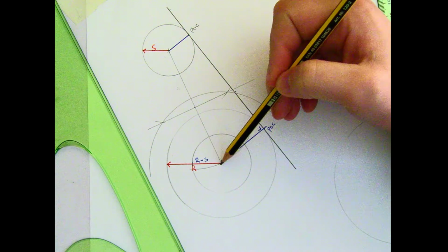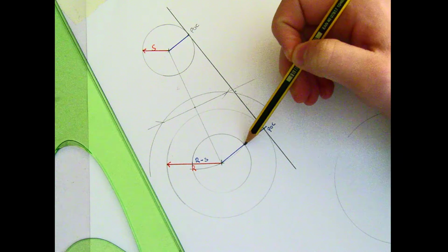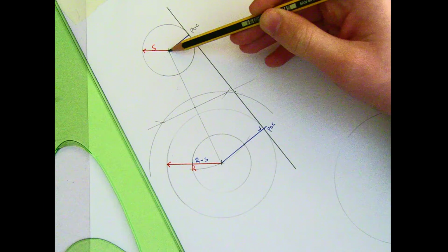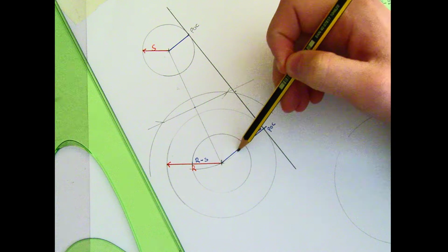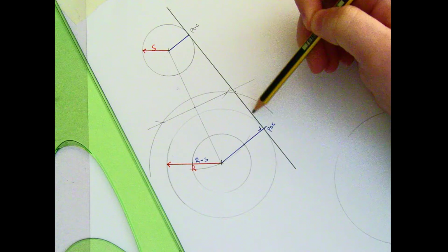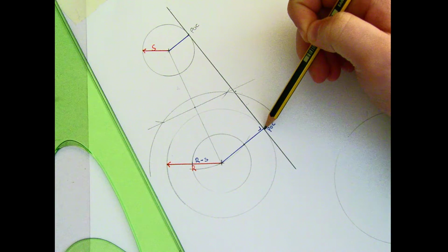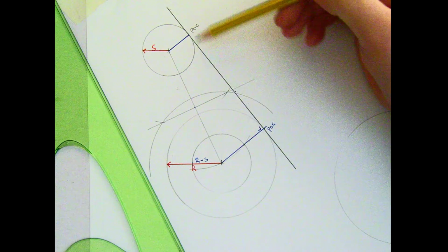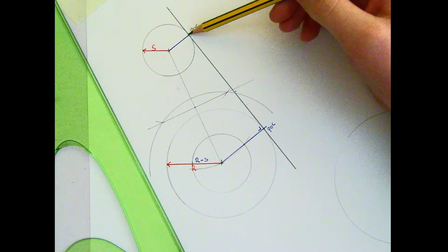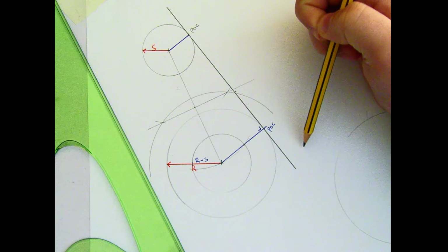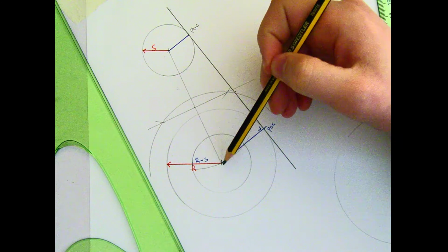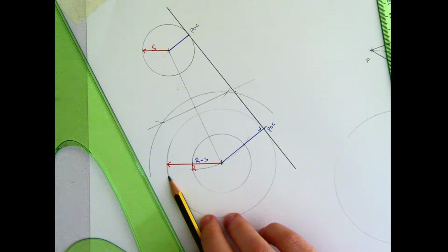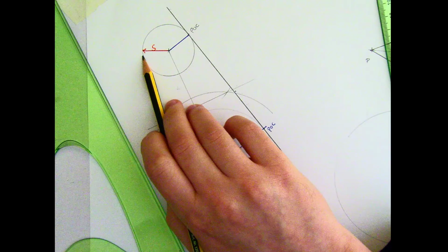join from the point to the center and bisect, swing an arc so that it touches the outside of my circle, giving me what would be the point of contact between here and this point. My normal is going to pass through that point from the center of the larger circle, giving me the position. That's one point of contact. My other normal from the other circle is going to be parallel to this normal, and that gives me my other point of contact, and now I can draw my tangent. There would also be a second tangent on the opposite side of this, extending from the point through my point of contact to a point out here somewhere, and that would also go back, joining back this way.